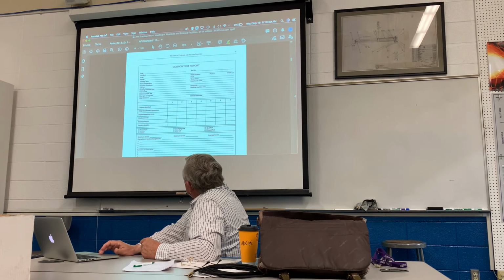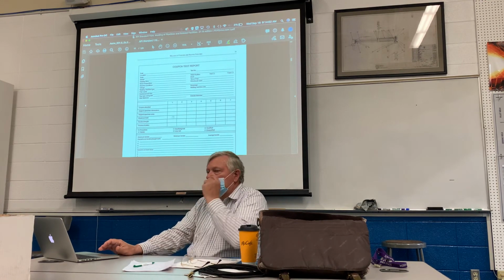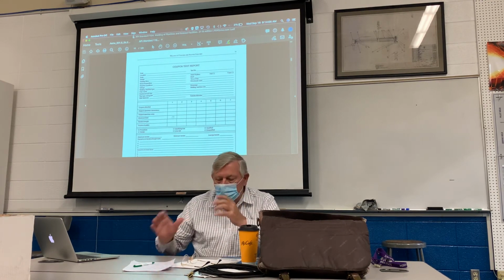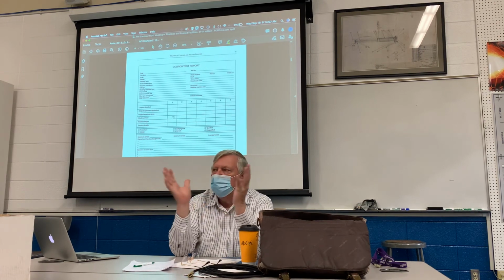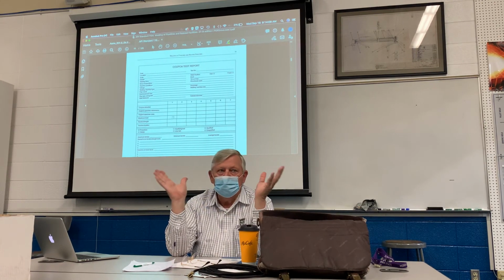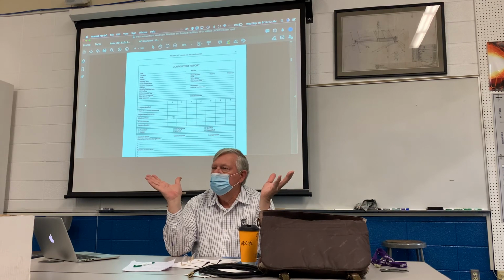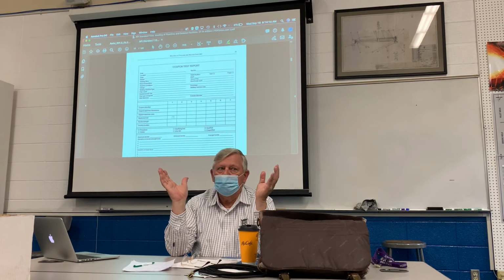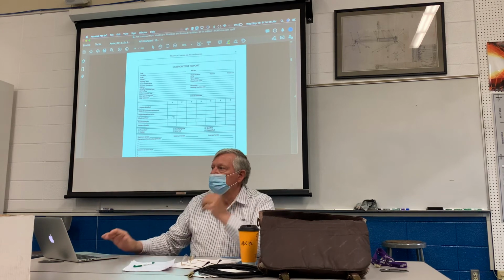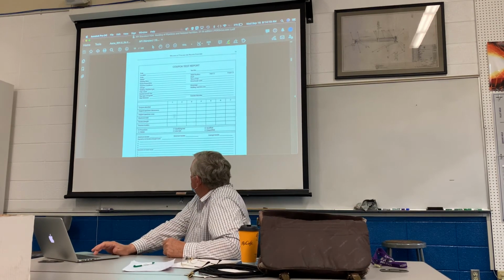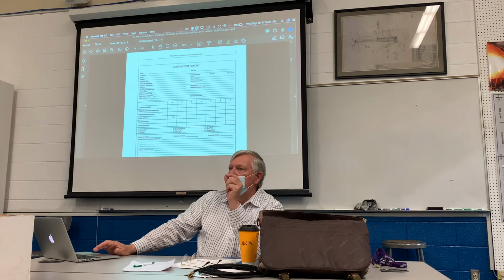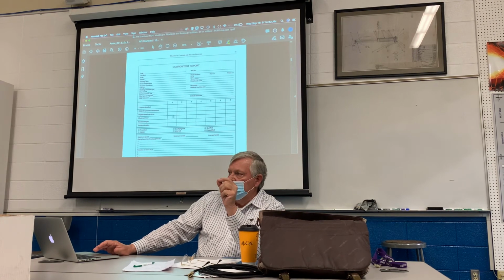And then these two indications here are going to be the tensile strength where it broke, but the maximum load is something different. Most tensile testers do not have a range that's going to show you on a gauge that this broke at 46,000. It's going to say that it broke at 7,000. So the load number is going to be the amount that's on the gauge of the tensile tester.